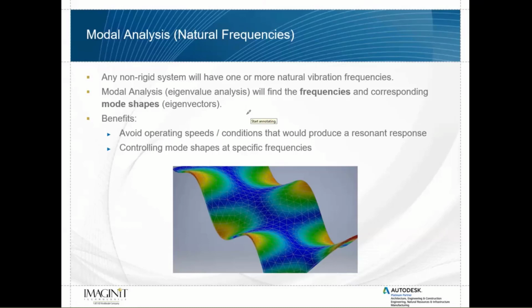You'll see more of the mass moving around and vibrating and increasing with each cycle to where you can actually have the structure sort of shake itself apart or potentially displace enough to loosen bolts, reduce the strength of some of your connecting components, and potentially cause a significant amount of damage. And it has nothing to do with the static loads coming into the system. It has everything to do with the natural frequency and the resonance response being created. So we're creating an excess vibration or resonant response that will lead to significant damage.